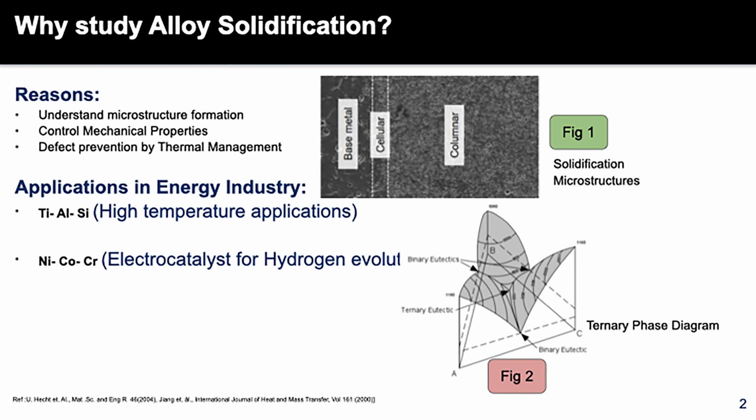Next, the keyword in the title was ternary. We are trying to develop a system that can deal with three components, also known as a ternary system, and even more than that. Figure 2, at the bottom, shows the equilibrium phase diagram of the three metal components in the system as a function of temperature and the metal composition. And we can see how complex a phase diagram like this is. Understanding this helps us understand the solidification process better.